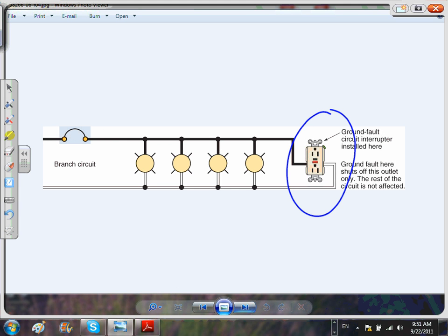You provide it right at the branch circuit. What's the advantage of putting it right here, by the way? What's the disadvantage of putting it on a branch circuit that has lights on it? If you trip it, what's going to happen to your light? Gone. By the way, can I put the lighting circuit in the kitchen on the same receptacles? No. These two small appliance circuits in the kitchen are circuits only for receptacles. You can't feed anything from it. No lights, nothing, with very few exceptions.